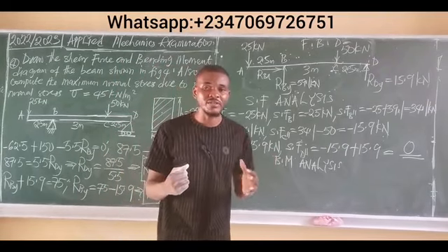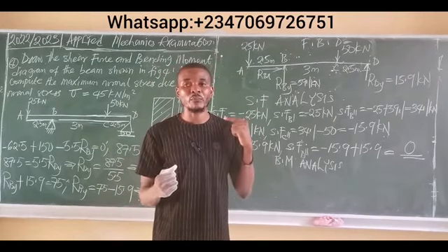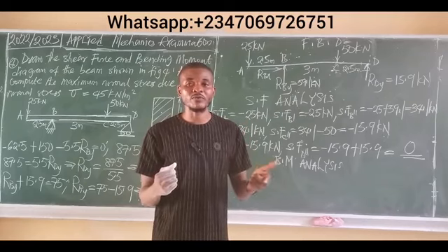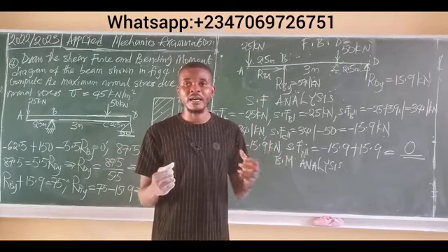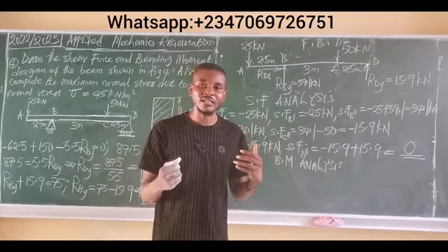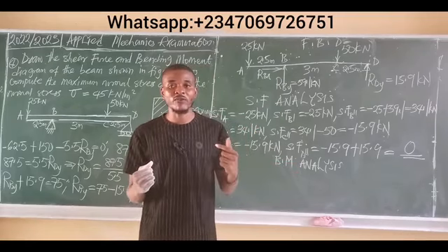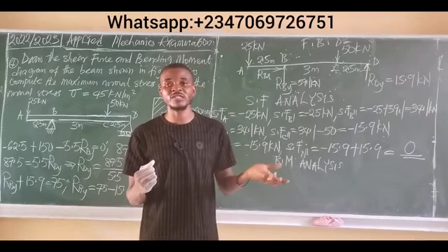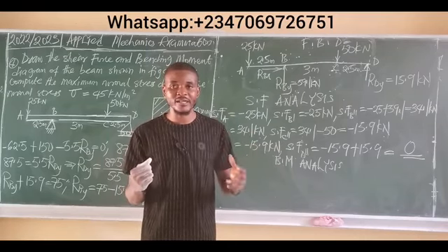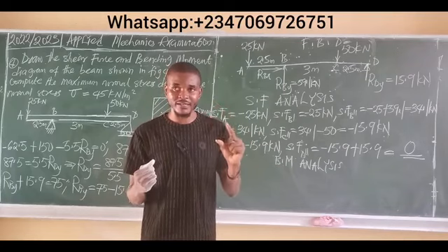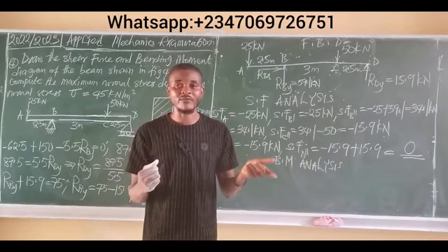Bending moment analysis simply means the stepwise summation of the entire moment of forces acting on a beam from the beginning of the beam at each point of the beam to the end of the beam. So you always start from beginning to the end. Mind you, whenever a force is acting downwards, that force produces a negative moment. And whenever a force is acting upwards, that force produces a positive moment. And also, at the end of every bending moment analysis, you must always have 0 as the answer. Keep it in mind. So if you don't have 0, it means you're wrong at the end of analysis.